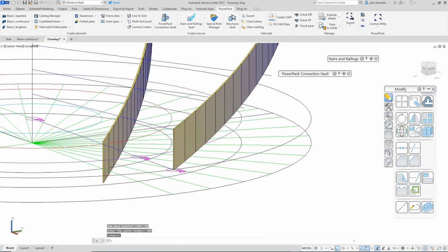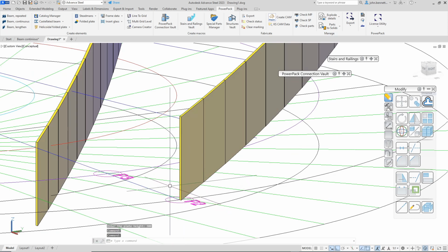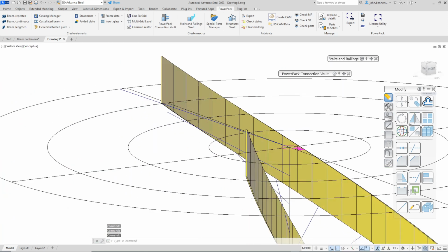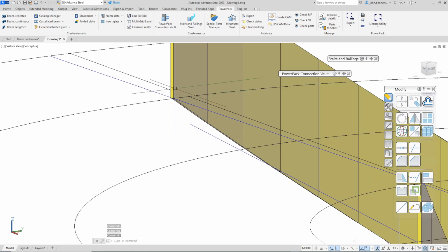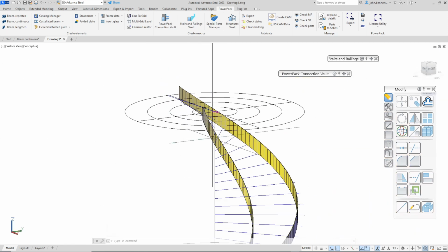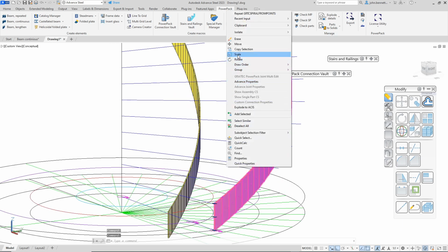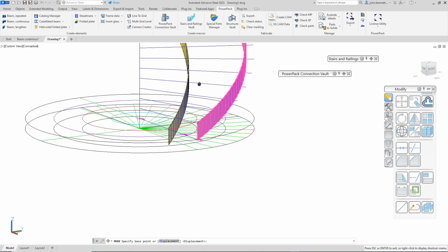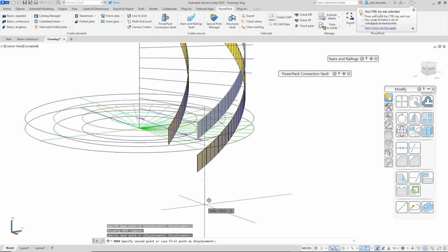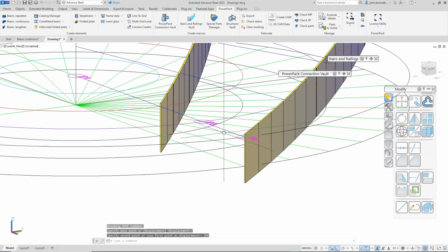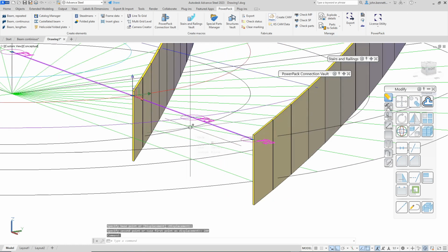So you can see that it came from point 2 here. It obviously went to the next diameter in, which was our point 3, and obviously it's gone to the height here. Obviously I used the setting out for that. If you want to move the object afterwards, you can move it quite quickly just using the AutoCAD move tool. You can pick it down. So maybe I want this to be 20 millimeters above my toe position for my first tread, which is here.